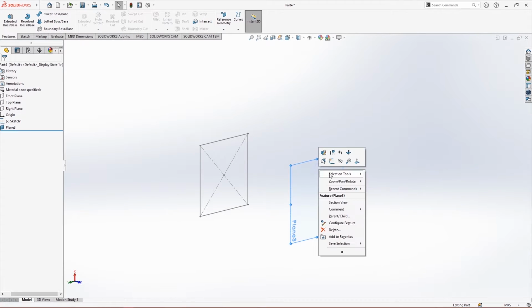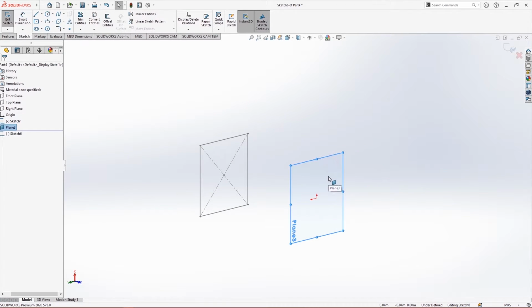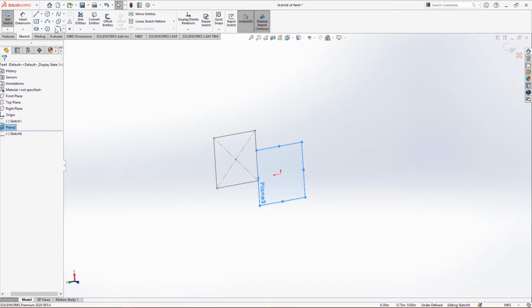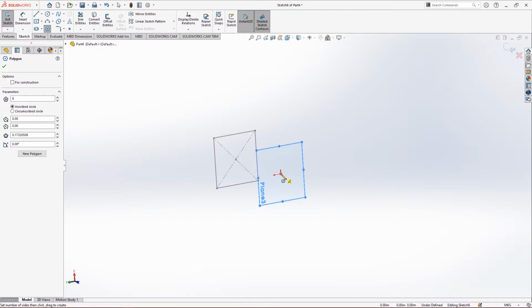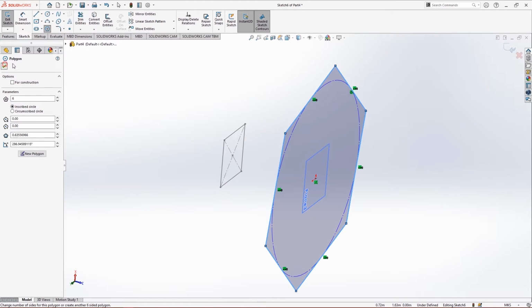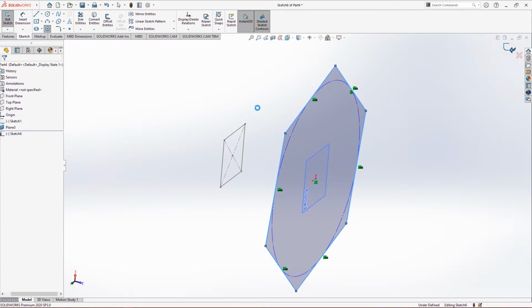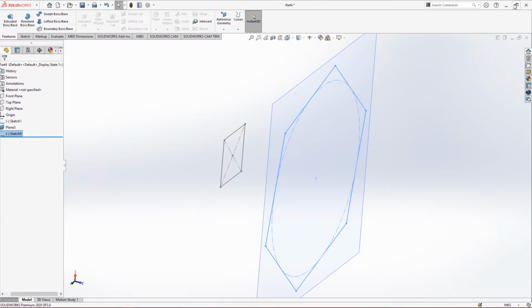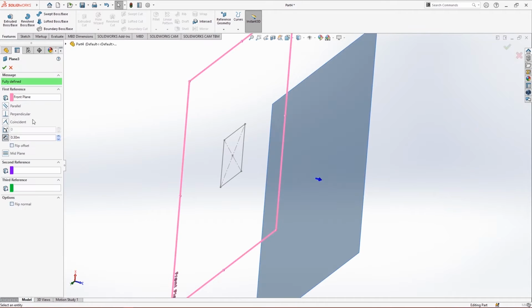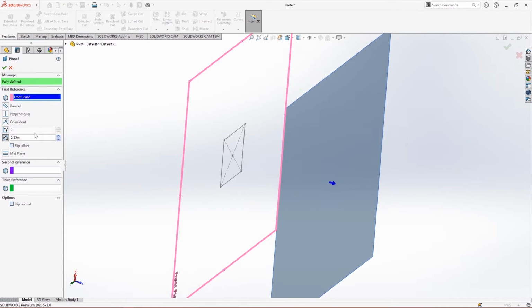Now I want to draw on this, so just right click and click sketch. So I am in this particular plane. Let's make a quick sketch here, a big hexagon. Okay, now one more thing, just get out of it. You can even edit the plane. Let's click on the edit feature and increase the distance. I want it to be around, like, increase it to 0.5.